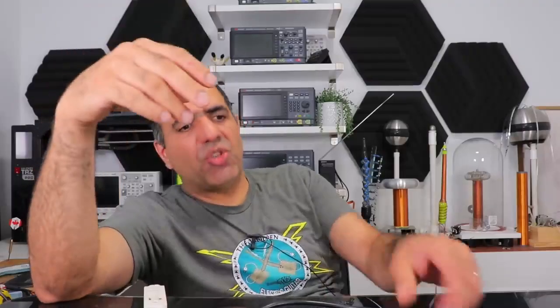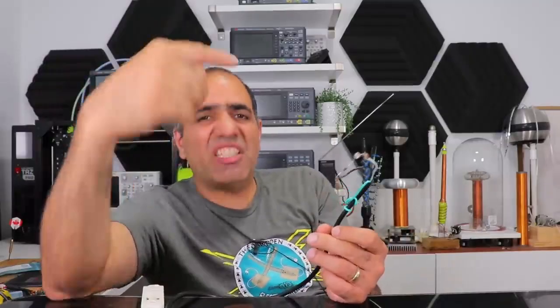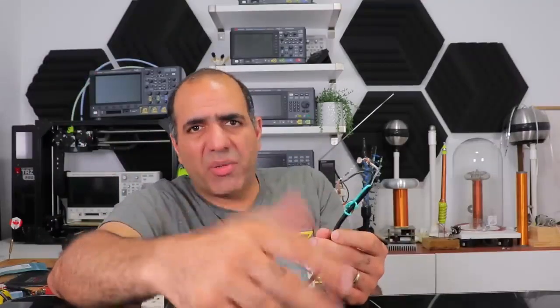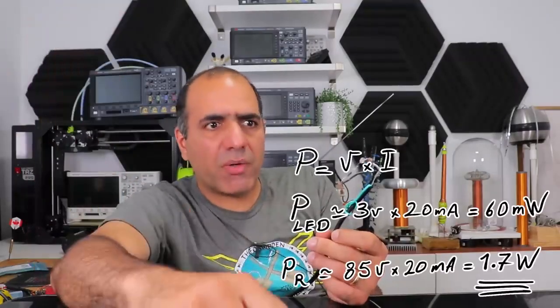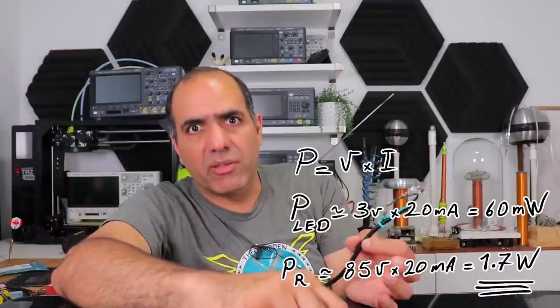See, that's the issue with driving LEDs with resistors, especially at high voltage. While the LED itself was consuming around 60 milliwatts of power, the resistor was consuming 1.7 watts and burned. So especially at higher power application, having a series resistor to control the current just wastes a ton of power.